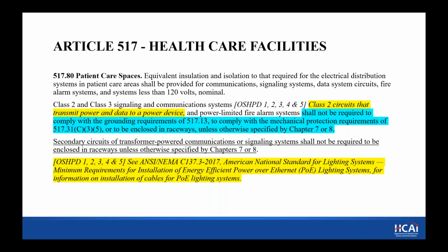The 6-foot flex from the last J box to the fixture itself is accepted in the code to not be required for mechanical protection, but that's just it. Just the last 6 foot from the J box to the fixture itself. Thank you, Jamie.